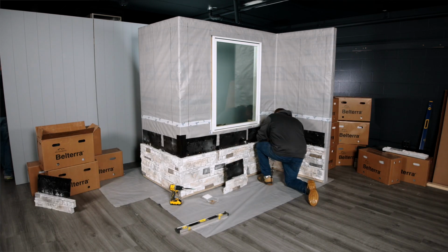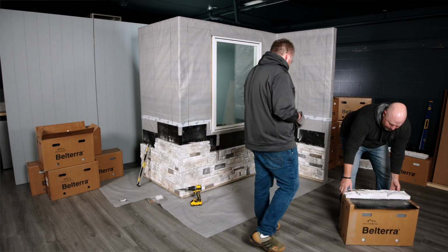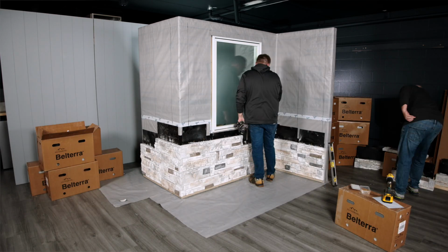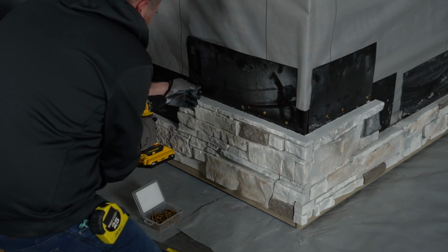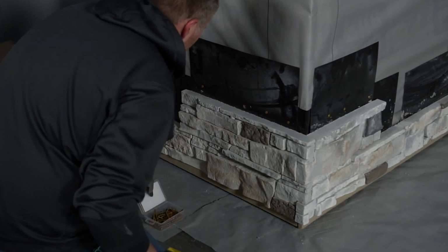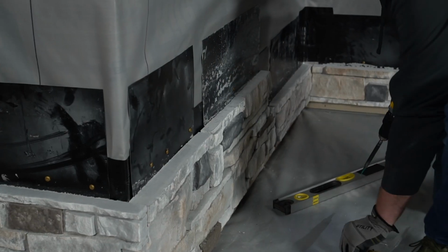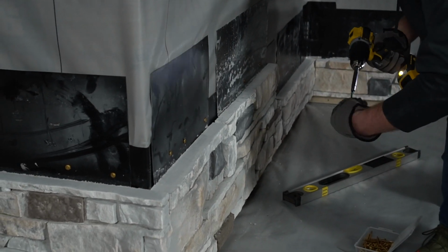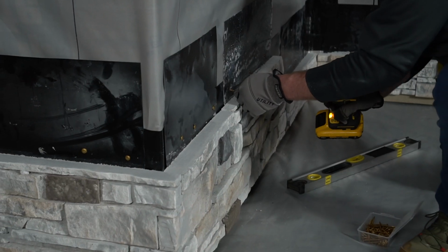Stair-stepping: corners and flats can be built up in a stair-step fashion once the initial course of stone has been installed. This technique improves efficiency, reduces installation time, and helps hide cut edges in inconspicuous areas. Set a starting edge from which you will work right or left. In the case of an outside corner, install the full outside corner, both sides, up to 8 courses at a time, following the directions for installing outside corners.